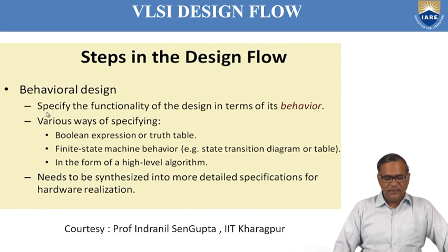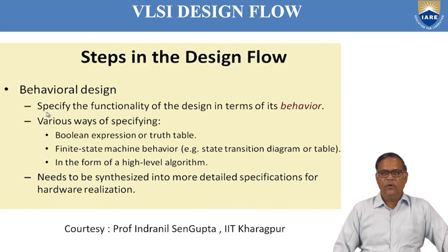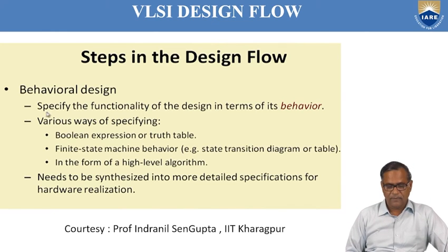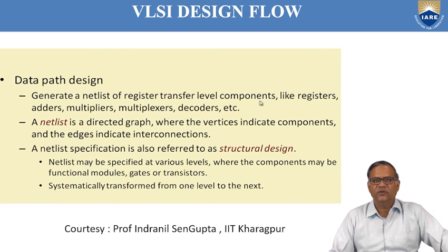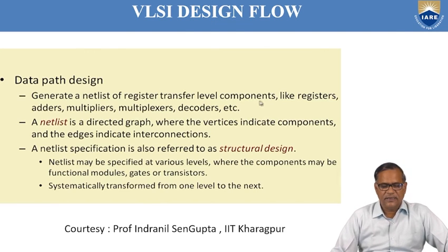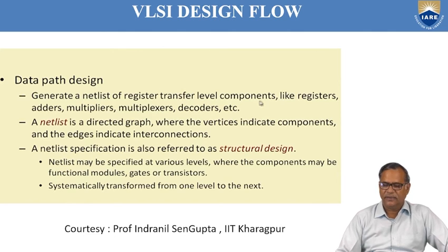This design needs to be synthesized into more detailed specifications for hardware realization. Next is the data path design. Here, this generates a netlist of register transfer level components like registers, adders, multipliers, multiplexers, etc. A netlist is a directed graph where the vertices indicate the components and the edges indicate the interconnections.